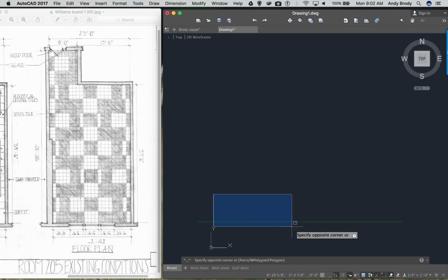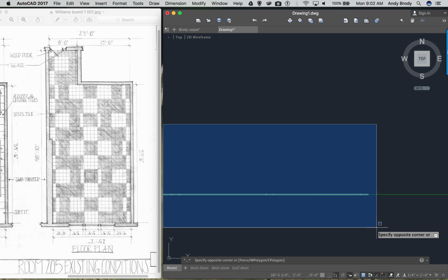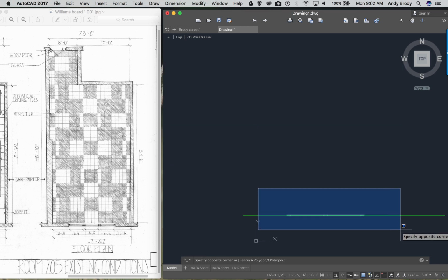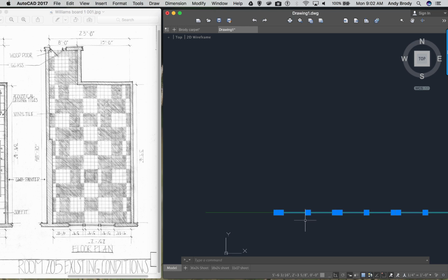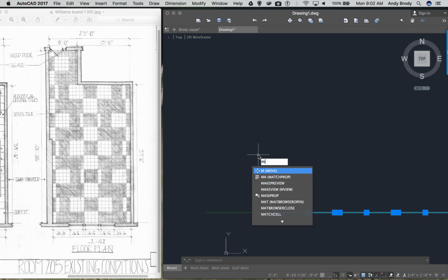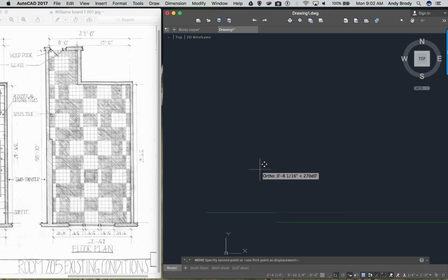Well, really what you'll see, if I use a selection window, see how there are a number of lines that are drawn here? I can use those lines to draw my window. I happen to know that the whole window is inset about 4 inches. So I'll change it to 4 inches by moving it down. And again, I will not be repeating commands that we learned last time.